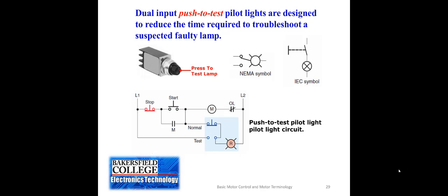In a critical environment where a light comes on that shows a dangerous condition, you want to make sure that you test that every so often. Sometimes it's part of the beginning of a shift of a worker, an operator. That worker is going to test all the lamps to make sure that they're in working order.